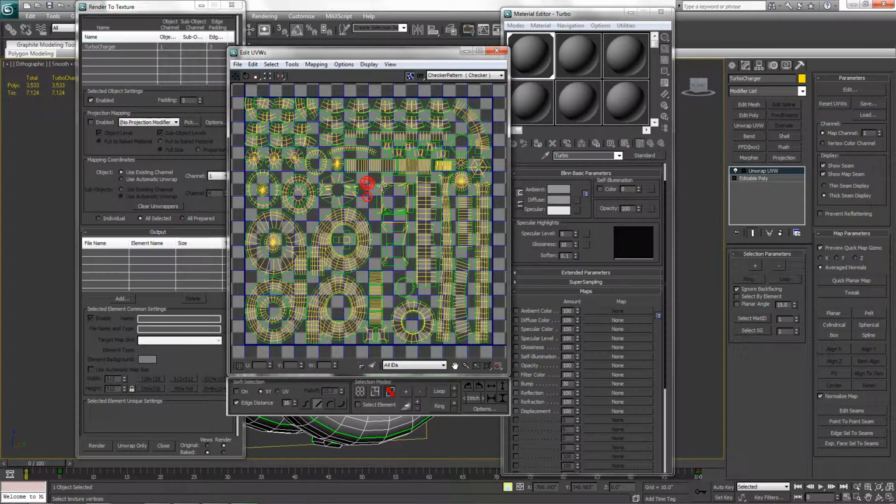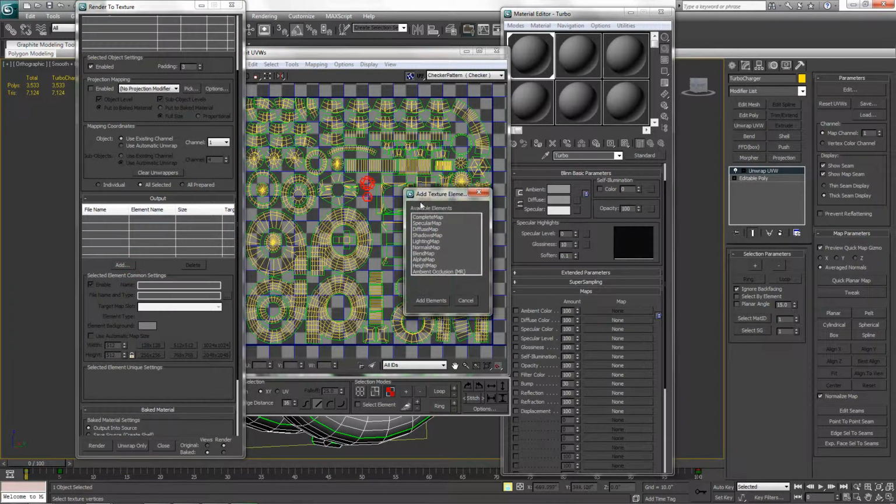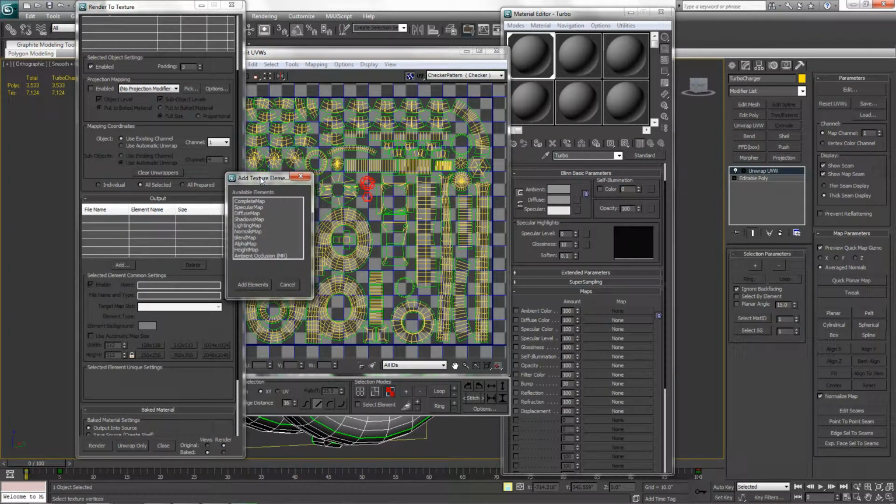They've been selected, and since this is a repetitive detail, we'll probably be painting something more specific for that rather than using output from the texture bake. So those are okay to have overlaps, but ideally try to avoid that on your main objects, as the output from Max can have some artifacts. So back to the Render to Texture dialog box.